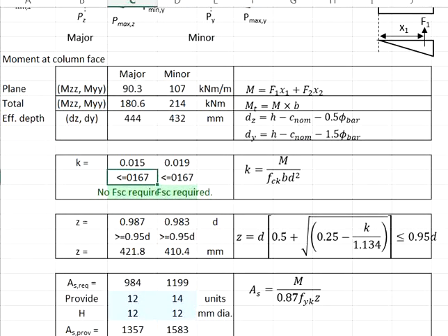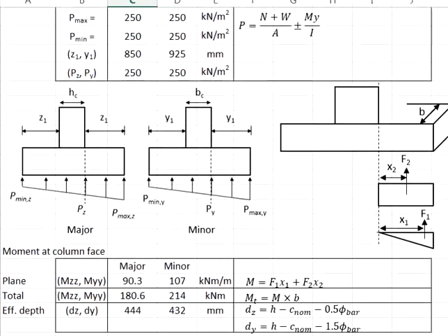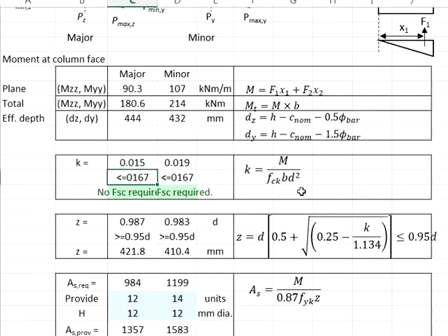However, in the case that you foresee there may be uplifting of the peg footing, then you will need to provide the top reinforcement bar, which in this case we assume that there is no uplifting of the peg footing. That means you only need to provide the tension reinforcement bar at the bottom of the peg footing.